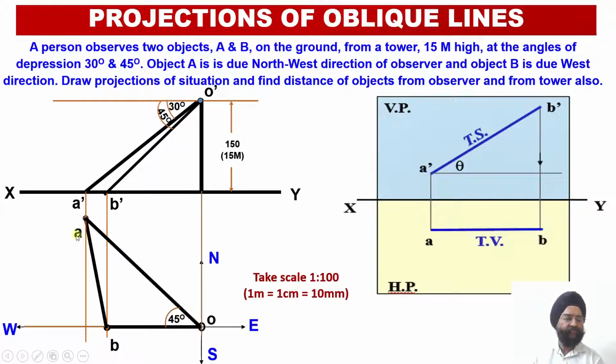So this is O, this is point A. Once we rotate it in this direction, the arc has to be extended up to the horizontal locus line which is emerging from point O. So we are drawing an arc of radius OA from the point O, such that this arc intersects this horizontal locus line. This point of intersection, the first rotation, will be A1.